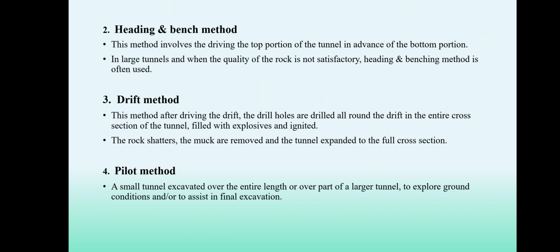Second, heading and bench method. This method involves driving the top portion of the tunnel in advance of the bottom portion in large tunnels, and when the quality of rock is not satisfactory, the heading and benching method is often used. Drift method. In this method, after driving the drift, drill holes are drilled all round the drift in the entire cross section of the tunnel and filled with explosive and ignited. The rock shatters, the muck is removed, and the tunnel is expanded to the full cross section.